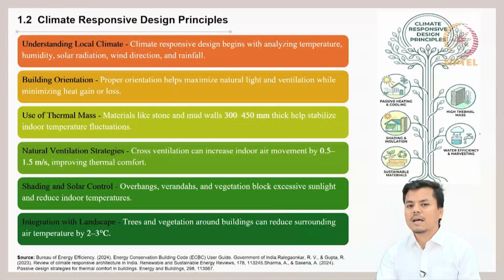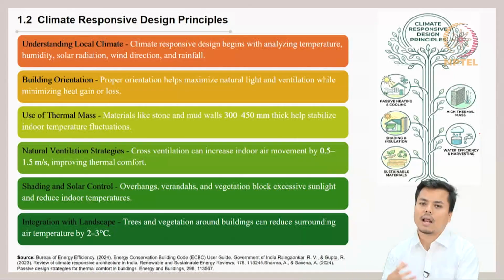Now let us understand how vernacular architecture is linked with climate responsive design principles. As I was explaining, vernacular architecture includes local climate as one of the important factors in providing strategies for construction. That is where climate responsive design features are developed. For this, one has to understand the local climate. Climate responsive design begins with analyzing the temperature, humidity, solar radiation, wind direction and rainfall.